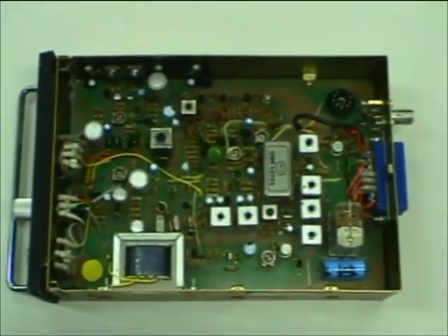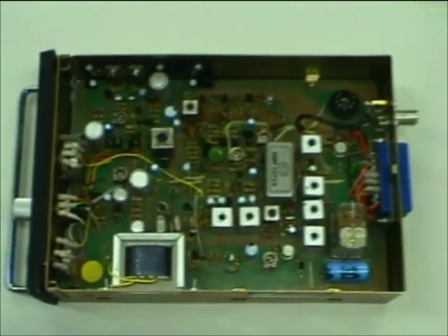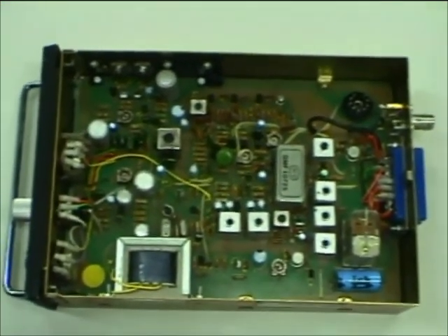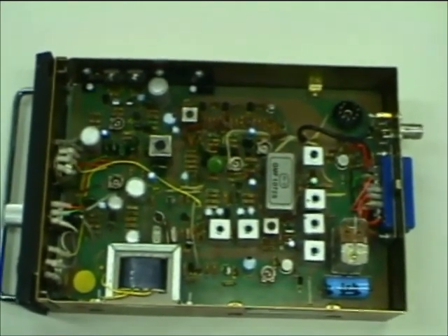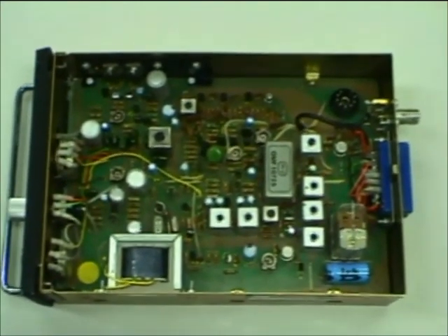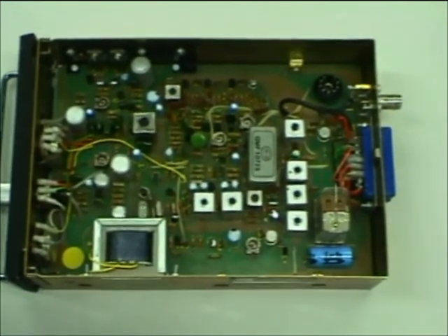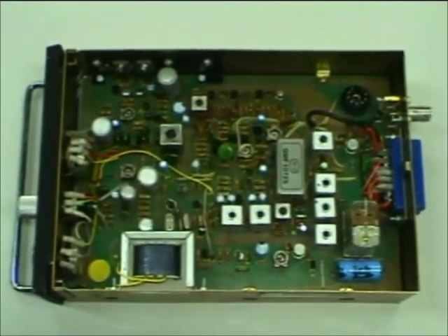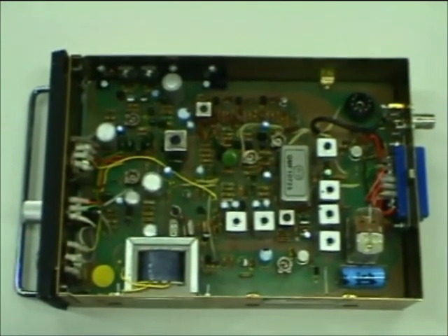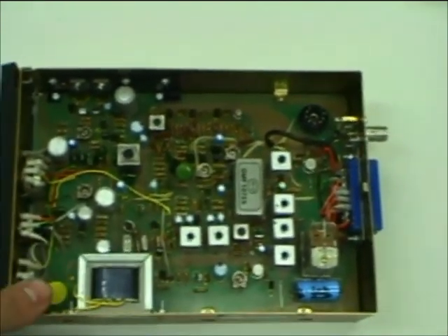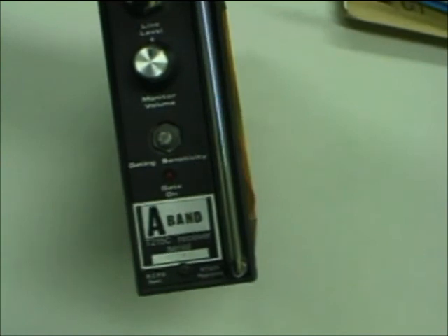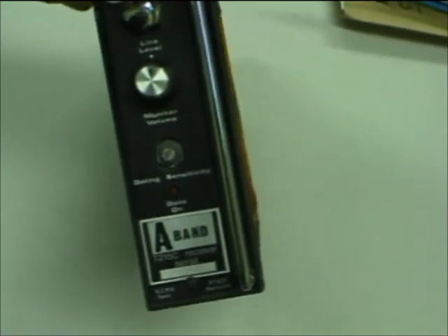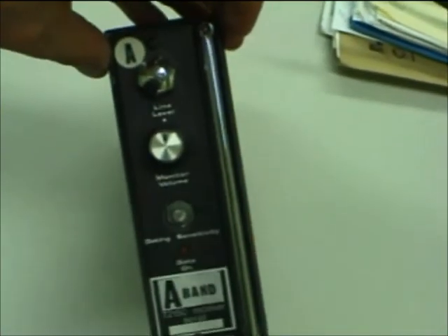I've showed it a few times before to show you bits and pieces in electronics, but it's not really physically like the receivers we use in amateur radio. Really the principles, the functioning of it, is pretty much the same, and it's all nicely open, so we can talk a bit about it. Here's the front panel of it, upside down. There you go. It says it works on A band, which in New Zealand is about 82 to 88 megahertz. It's designed to work over that range depending upon where you set it.